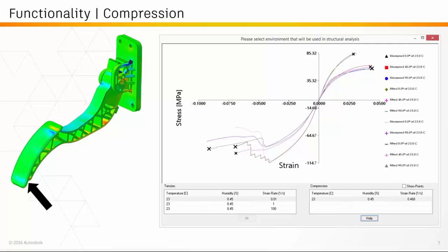When a material goes into compression, though, we typically don't see a large failure or rupture event in which the load carrying capability of the material reduces instantaneously like we do in tension. Really what we see is the material begins to lose load carrying capability, as we're seeing in the fourth quadrant on the plot. And once it loses load carrying capability, it continues to plasticize at some reduced load level.